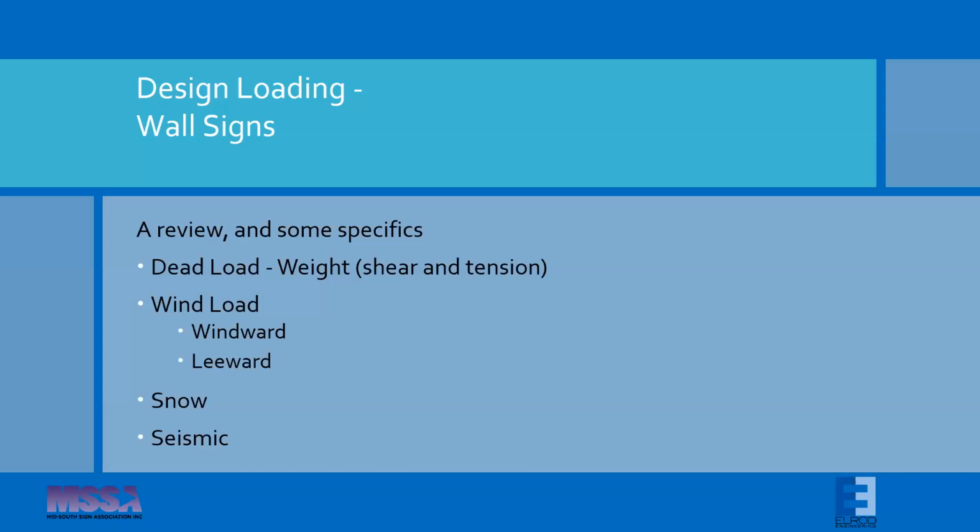Due to the height of the hotel, the snow loading at the building wall, so at the back end of the canopy, was over 30 pounds per square foot due to the drifting that was applied. That is starting to get significant and actually even resulted in a change in the internal framing of the canopy up against the wall in order to withstand the load.